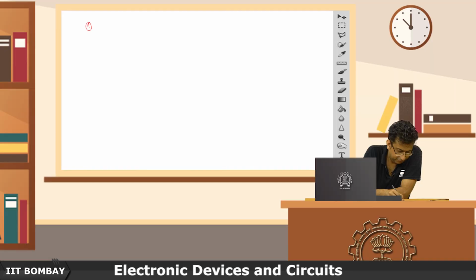So now I will talk about how this Schottky behavior converts into ohmic contact for this metal to n-type semiconductor case, and I will show how this diagram changes. So let's consider the first case of low doping, then medium doping, and the third case of heavy doping.